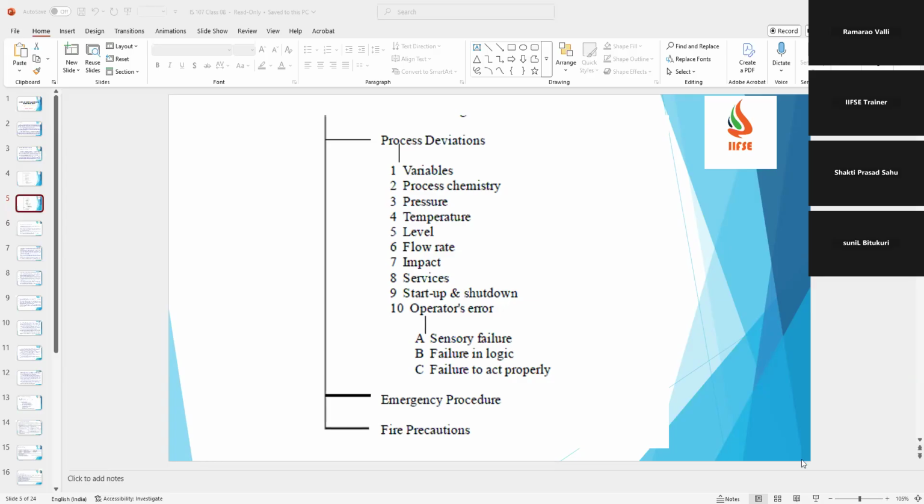Yes, perfect. So basically, the alarm may come. Sometimes they keep a manual alarm also in the emergency control centers, especially, where it is a kind of pedaling: we just rotate it by hand, and there also you get the alarm or hooter. So in case of any fire emergency, if any fire sprinkler activates, or any smoke detector activates from smoke generated, and also the other case, the manual call point. You will see the manual call points at every emergency exit, on the right side or left side.